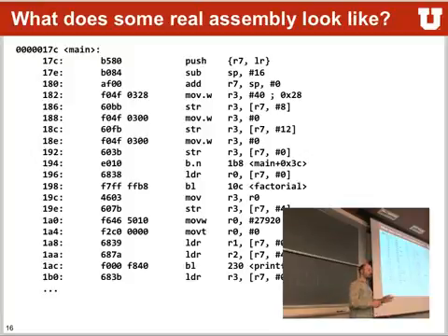We will talk about the stack a little bit later, but basically the stack is where the stack pointer is pointing to. Remember, in one of the registers, the SP, the stack pointer will point somewhere into RAM, and that's your stack. And the push, all it will do is take these two registers and store them into the address of where the stack pointer is pointing to. So once we do a push, what happens here with sub SP, 16? Moves the stack pointer down. Then we add our R7, SP, 0.